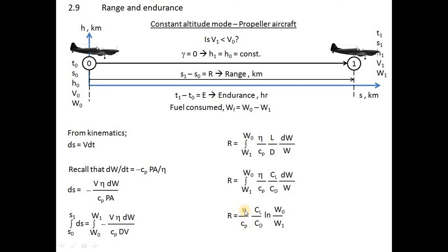Propeller efficiency at maximum, and minimum fuel consumption, power specific fuel consumption. This is subject to the fuel it can carry. The more fuel it carries, the bigger the difference between W0 and W1. So you can see, if an aircraft uses a different engine, it needs a different requirement for it to fly the longest endurance, in other words the longest time in the air, and also the longest range.